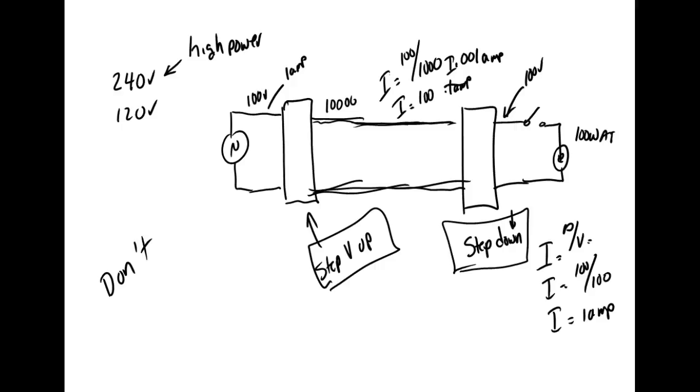What do we use 120 volts for? Well, all these outlets right here are 120 volts. 120 volts is a heck of a lot safer than 240. So what do we use high voltage for? Well, if you want to work for U.S. Steel, they have 6,000 volts available at that plant to run some 3,000-4,000 horsepower motors. If I was going to try to run that on 240, the thickness of the cable would probably be as high as this roof right here. But if they run it at 6,000 volts, then they can use smaller conductors.